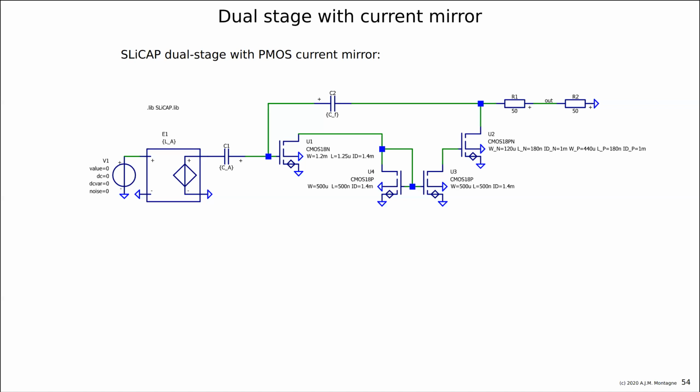Can you imagine how you would need to do that in LTspice? You cannot plot pole-zeros. You have to read it from both the plots. But sweeping an operating current is not as simple, because all the biasing should be adapted to do so. Here, it's just a parameter, and the small signal parameters of the transistors are quite accurately related to the geometry parameters and the operating conditions.